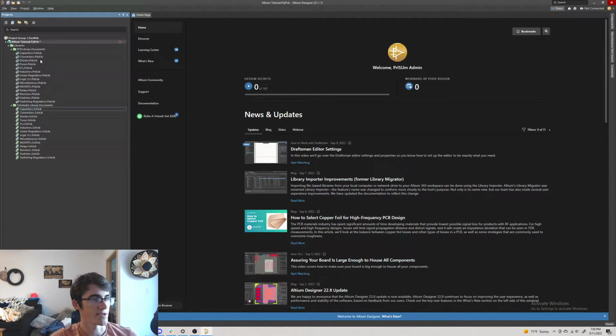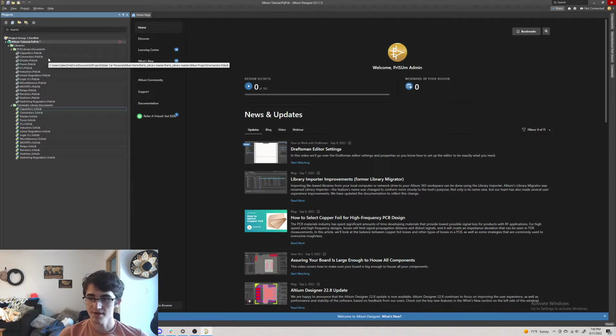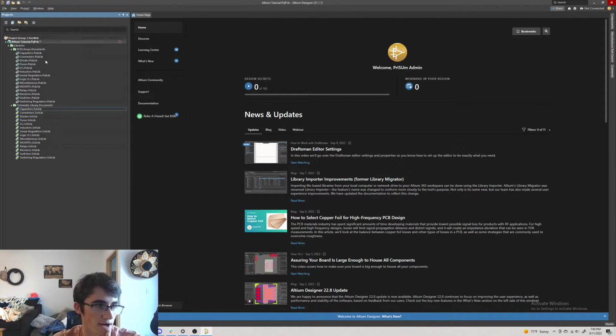But then for the PCB file, it's going to be what's called a footprint, which is normally some size rectangle that you'll actually solder the resistor to, and they're surface mounted or through hole resistors, so it kind of varies on what the size of this could be. And if you're unsure of those, there's general practice sizing for those, like 0805, 1206, and so on, and you'll get a good example of these in here. And let me just open one of those up to show you.